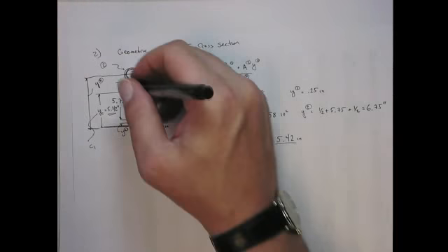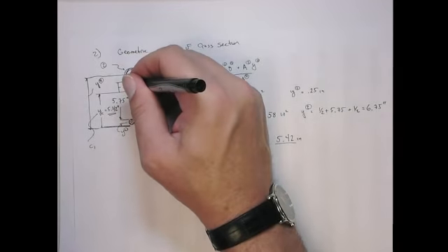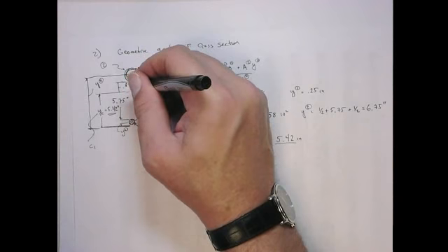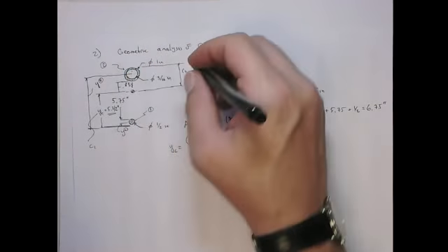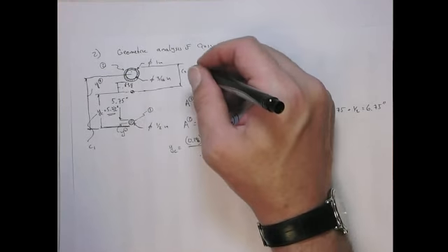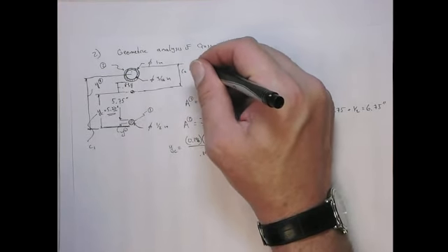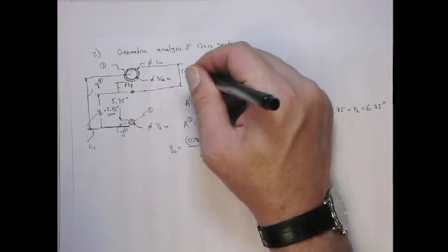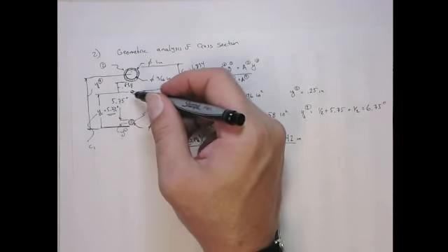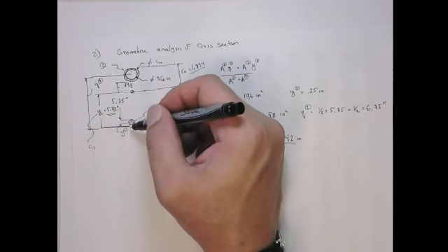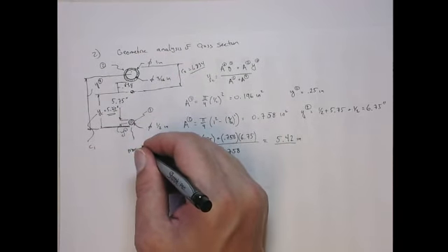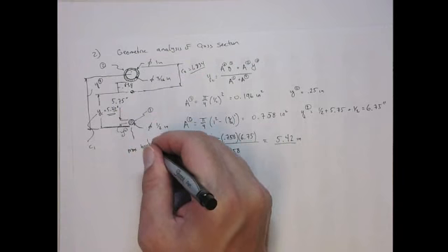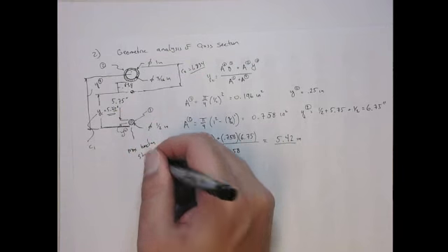So this distance here is going to be 0.834, and then we're going to add on to that another inch for this diameter, so that's going to be 1.834. So those are our two C's. So obviously the greater C is down to this point, so this is where we're going to have the max bending stress. Right at that point, okay?